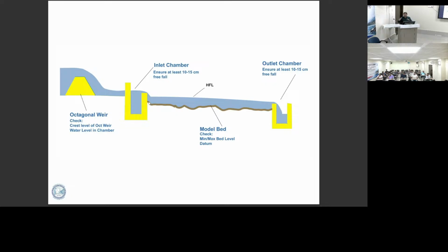Discharge and head, these two things you have to work out repeatedly, iteratively, making a table like that, until at one instant you get all the criteria satisfied. Space you get, discharge is sufficient, then head also you get. Then you have to decide. This is for geometrical similarity.